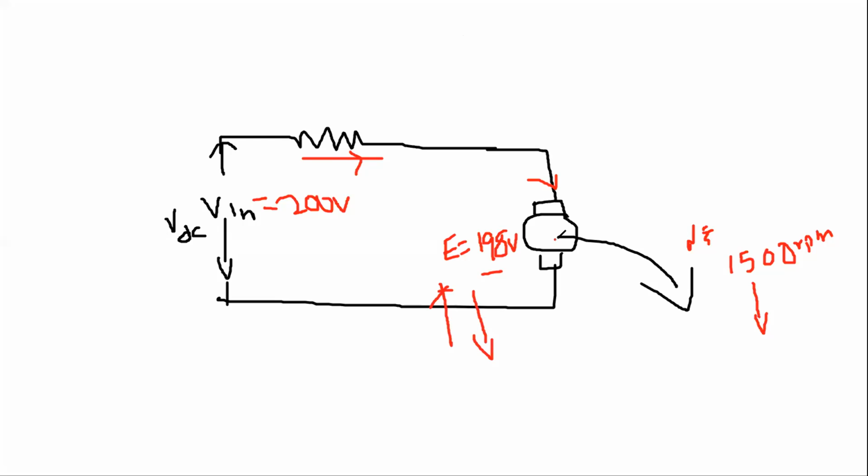You can see here, the machine is running with 1500 RPM speed. We have different thoughts: we can focus on DC machines, and AC machines also. Some people want to develop DC machines in their electric vehicle. At that point, we need to know the machine operation, whether it is operating effectively, and what the drawbacks of that machine are. If I use this particular machine, can I give more benefits to the customers or not? So if you select a separately excited DC machine, it runs at 1500 RPM and the induced EMF is 198 volts.